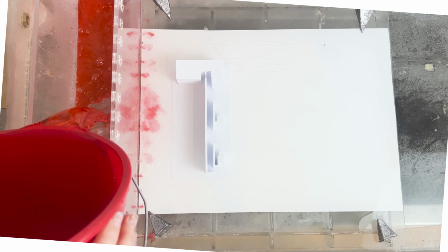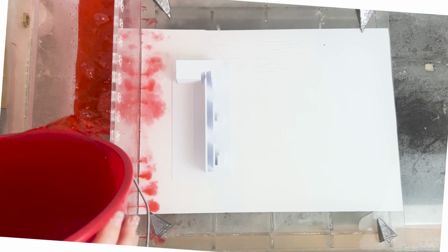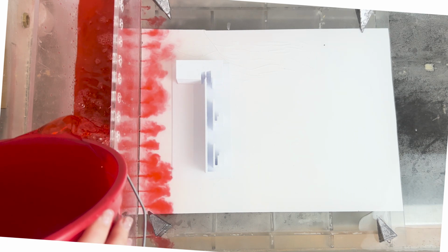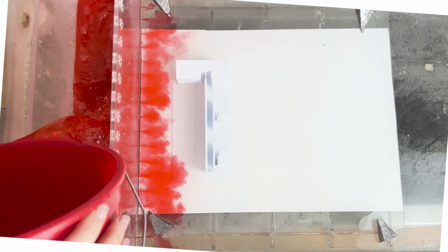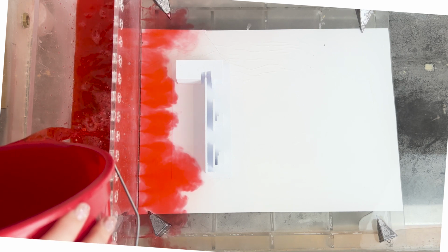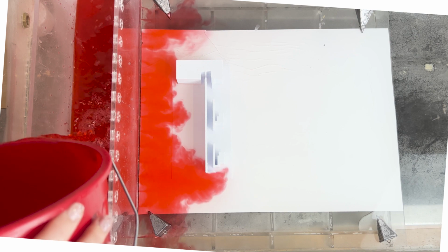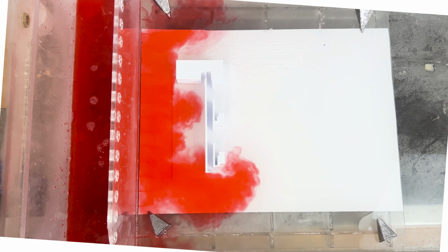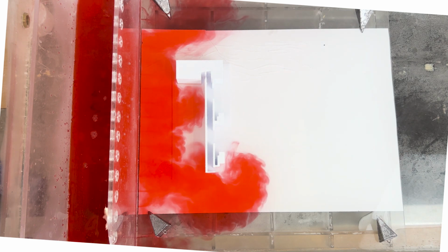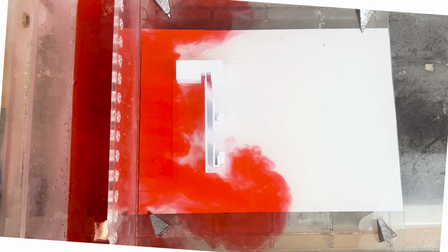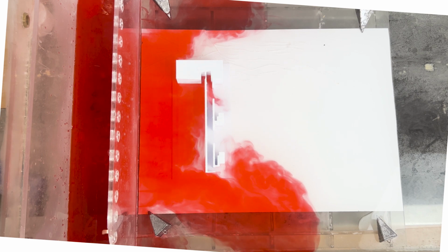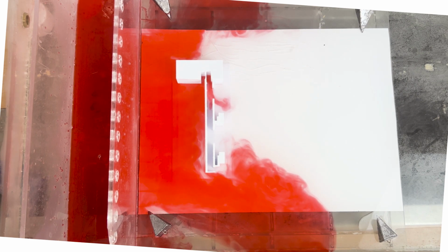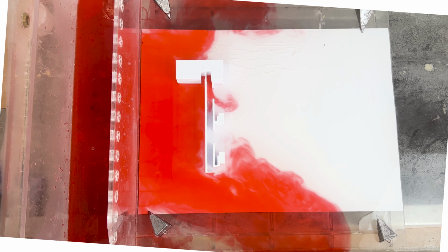When observing this test, we began to notice that initially we had some interference at the top from the food coloring immediately rushing up and over, leading to some obscure results that could occur. But in addition to that, you still can see the double skin facade working as intended. It enters in through this bottom channel that would be in the ground and starts to come up and through, exiting out through the first window. It takes more time to get to the second story window, but then you do eventually see it start to make its way up there slowly and surely.